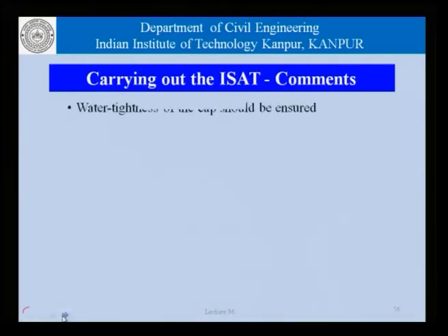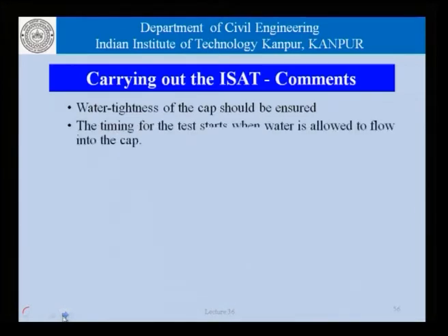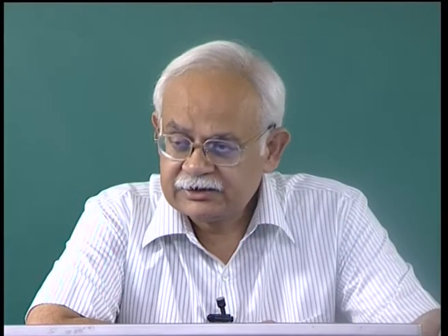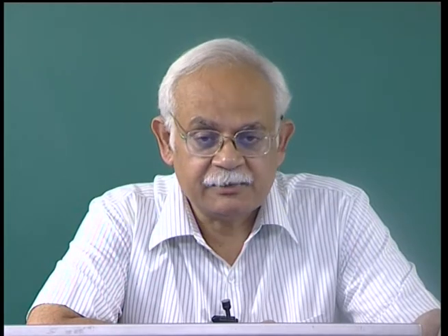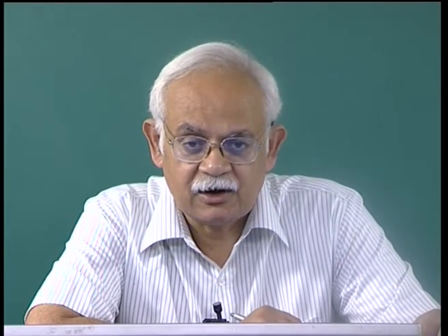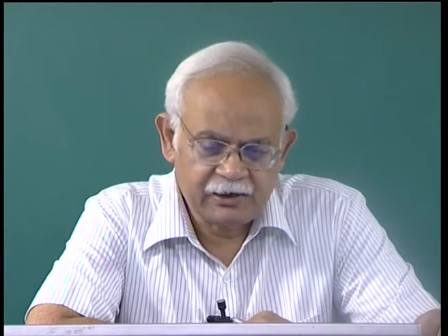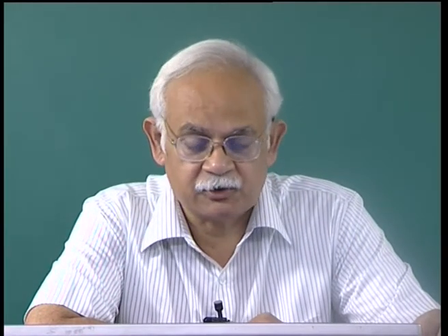And finally, as far as some comments on this test are concerned, we must ensure that the cap that we use is indeed watertight, and the timing for the test starts when the water is allowed to flow into the cap. And the test needs to be continued for different periods of time depending upon the movement in divisions of the capillary. So, in this case as well, we can talk in terms of quality on the basis of the divisions that the water moves in the capillary tube in a given time, or the time that it takes for the water to move through a certain number of capillary divisions. So, depending on our convenience, we can use one or both of these measures.